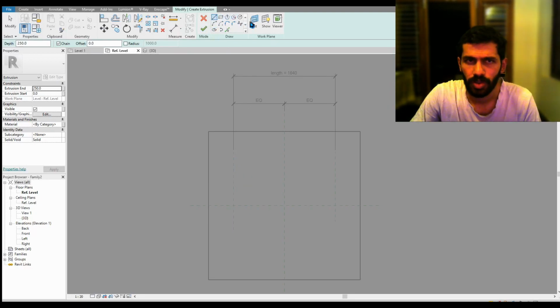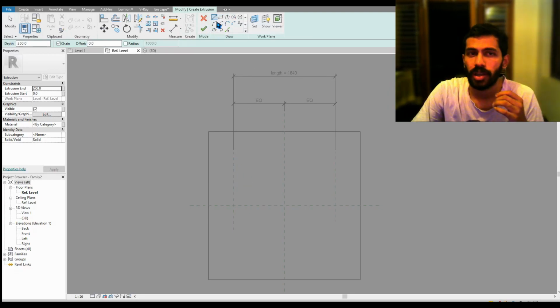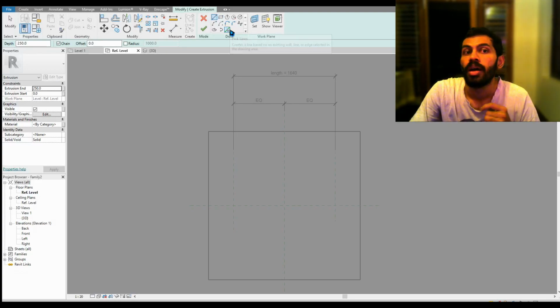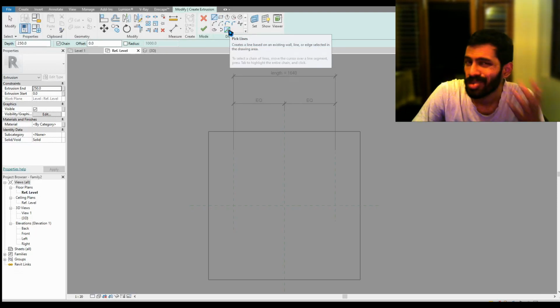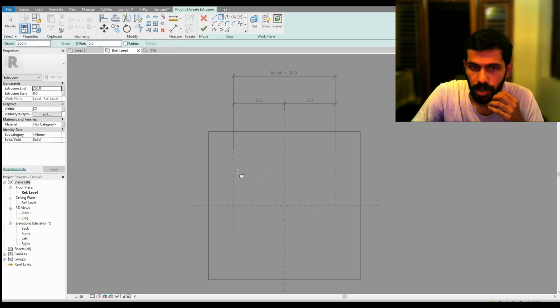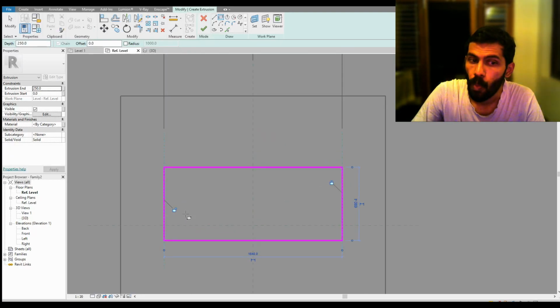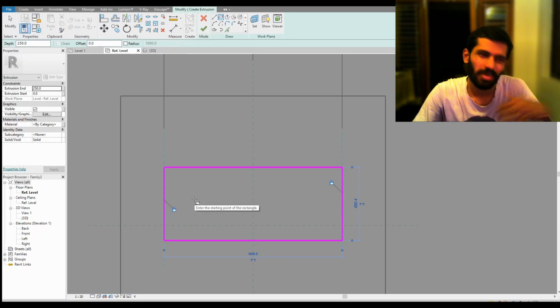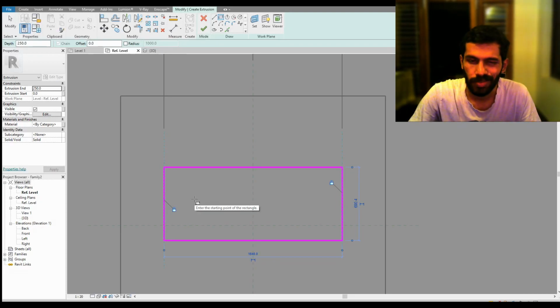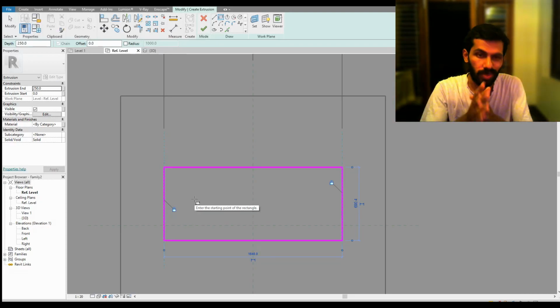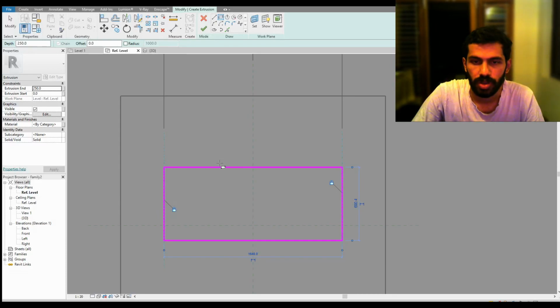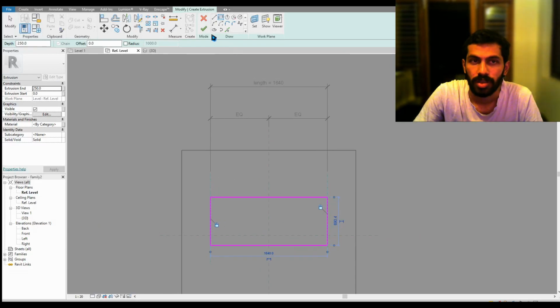The last step is that you can get into Extrusion, and I would like to use any of these options here. Either you can make use of Line, Rectangle, or Pick Lines. For simplicity, this is a rectangle, so I'll be making use of a rectangle here. It's quite important to lock this extrusion to the reference plane. In some cases it's okay, but in some cases, if it isn't locked, the length will change without considering the extrusion. So that's the simple case.